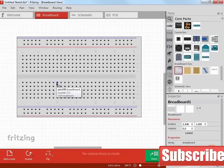Each column, 1 to 30 for this breadboard, has contacts in rows A through E common and contacts in rows F through J common. Any device inserted into the same column in rows A, B, C, D, or E will be connected, and any device inserted into row F, G, H, I, or J will be connected if on the same column. The rows are not connected.